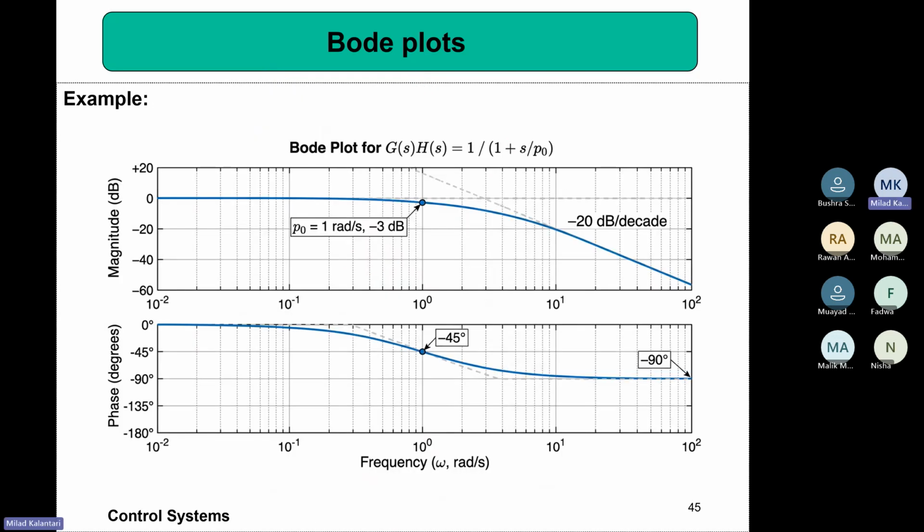So again, this is showing the Bode plot for another single pole, right? At this pole, as you are seeing, we first plot these asymptote lines. And then we do not even need to show this negative 3 dB point, which is at the pole, but we need to know which slope this is dropping with.